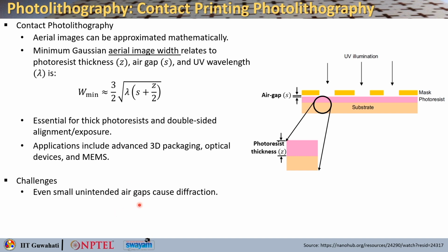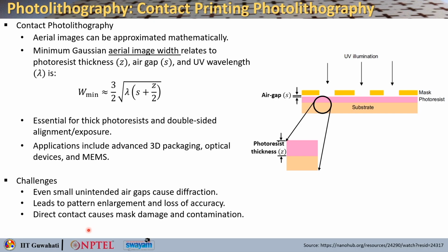There are some challenges. Because of these small unintended air gaps, there is a diffraction effect. In some cases the patterns get enlarged, or there is a loss of accuracy, and most importantly, because there is direct contact, the mask will get damaged and contaminated.